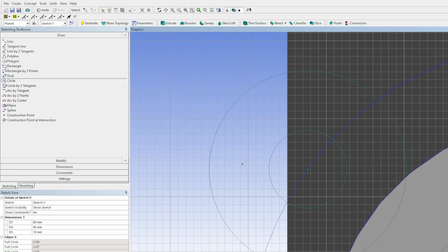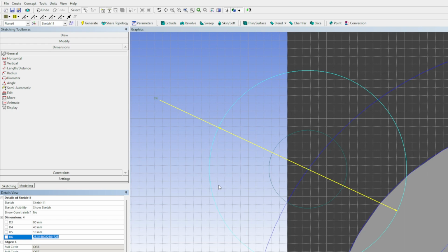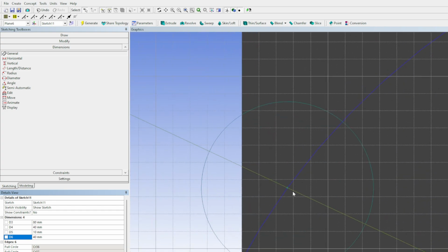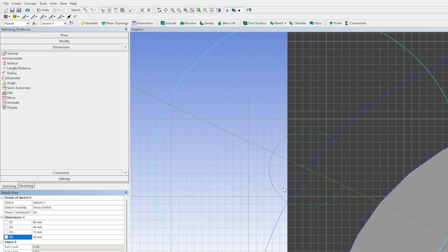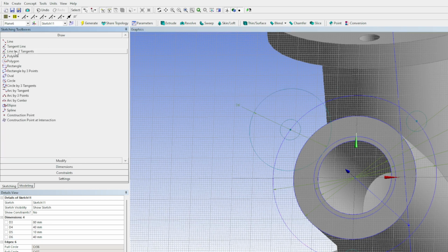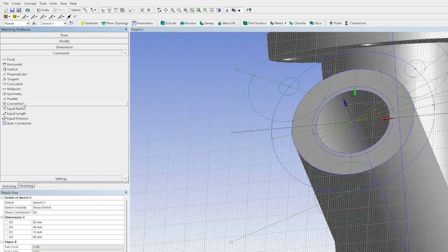We're going to click this out here, and this dimension is going to be, so this is our diameter. The problem statement calls out a radius of 20, so we're going to need 40. And the other thing, okay, it looks like it was just a little bit of a visual glitch there. So now we can go ahead and do that again. But this time, we can just kind of click our 3 circles out and then set them equal to each other with a constraint.